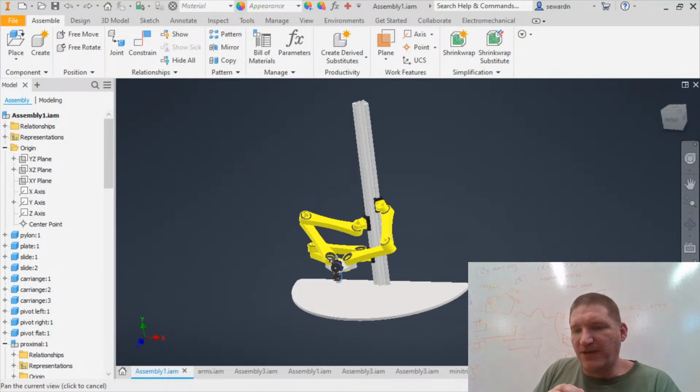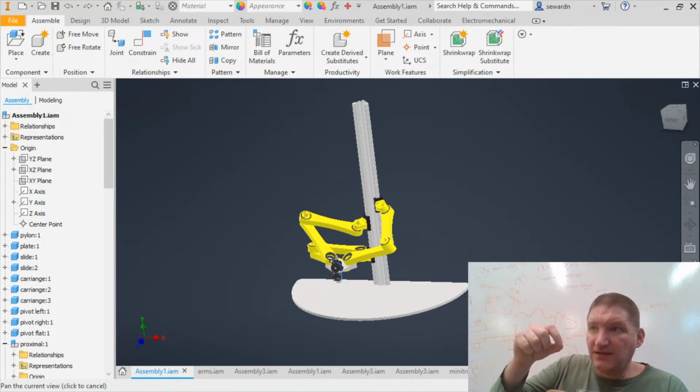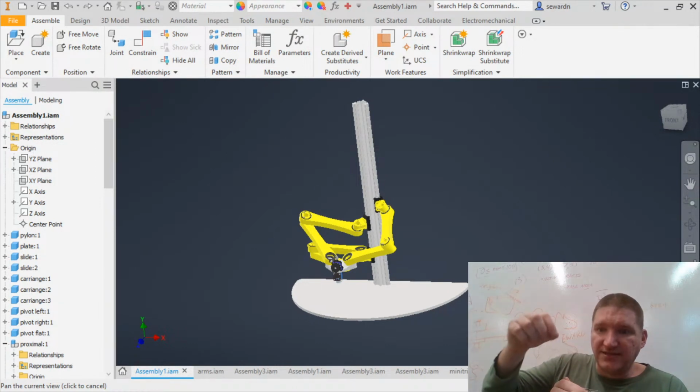Is it good enough for bed probing? I think the consensus is no, it's not good enough for bed probing, for two reasons. One, it's only down to like 1 or 2 steps, and I think you lose your position after you do it. So you would have to home, which using StallGuard to home is not as precise as using end stops, and then you would have to go back and probe again. Maybe I'm wrong, but I think it would be a very long process. I'm going to use an IR sensor.